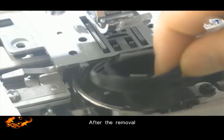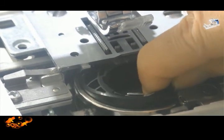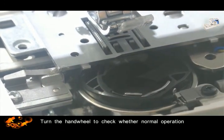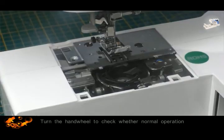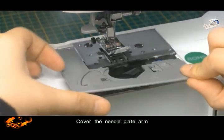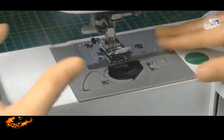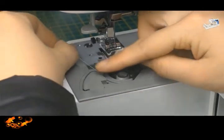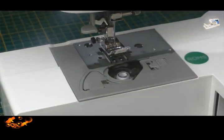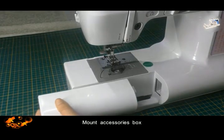After the removal, load the hook normally into the bobbin case. Turn the hand wheel to check whether it operates normally. Cover the needle plate arm. Add the bobbin. Put on the transparent bobbin cover. Mount the accessories box.